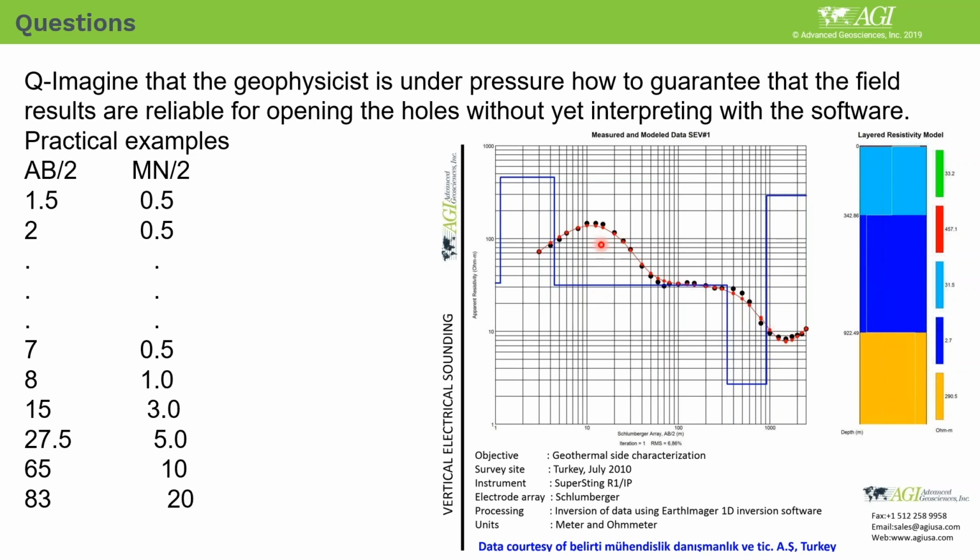Apparent resistivity cannot be used for interpretation, except when you do a soil sample measurement or in situ measurement, very homogeneous, like a soil sample in the lab and in the soil box. Yes, that's exactly the same thing. But in this environment, it's not homogeneous, and there are also directional variations. So that means you cannot use it. You have to invert it.